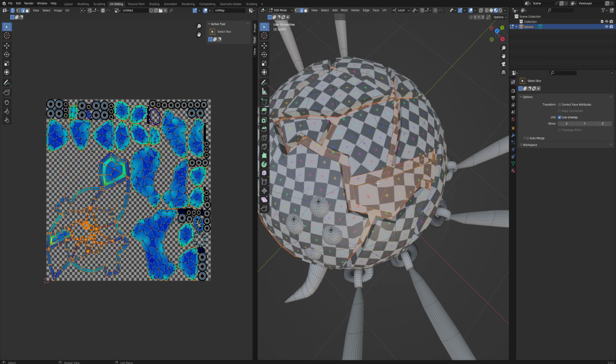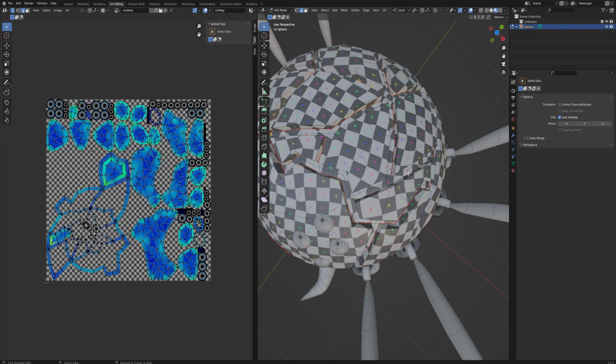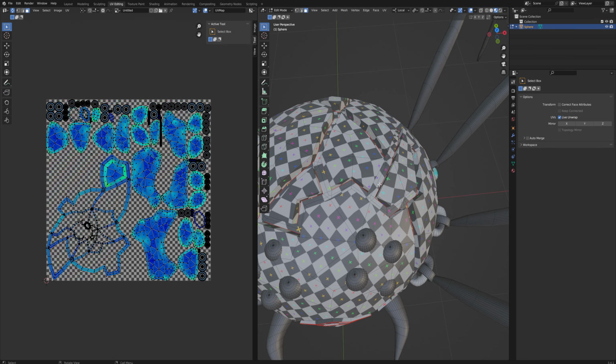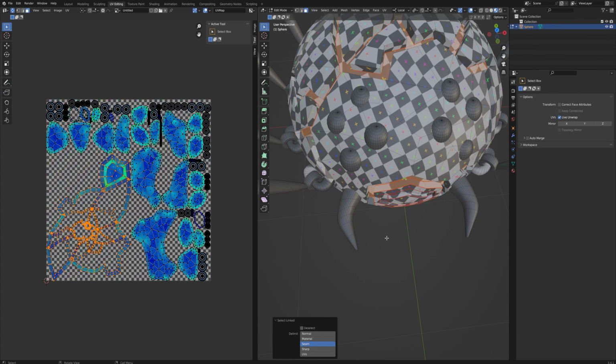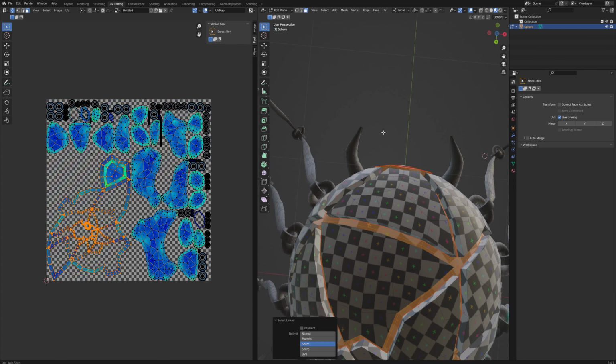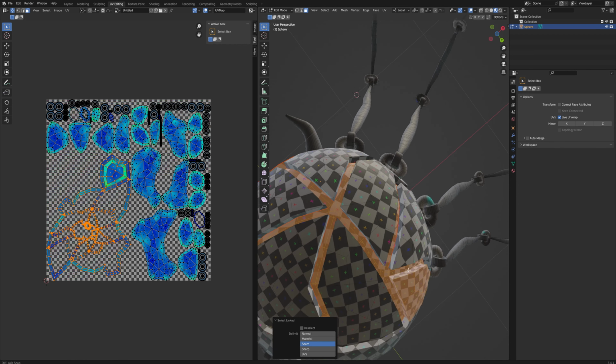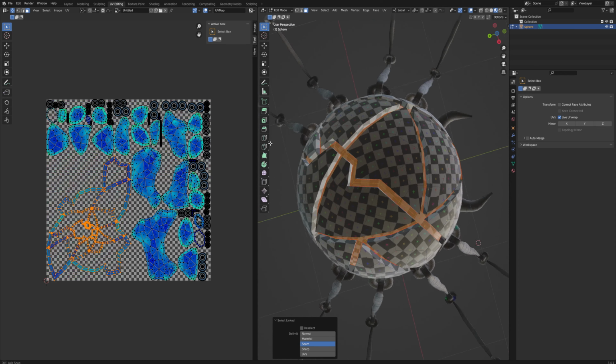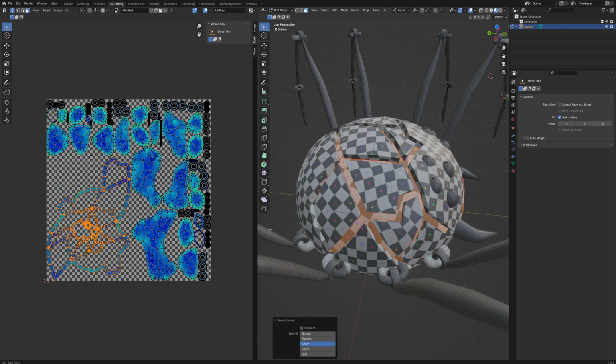Going back into edge select mode will then allow me to quickly unwrap around this island. Then pressing 3 to go back in face select mode, selecting all of the connected things for the channel down below. And this seems to be, we've got another one over here. And now when we look around, there's nothing else linked to this.